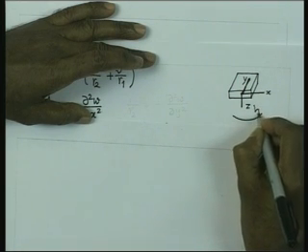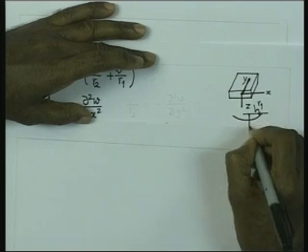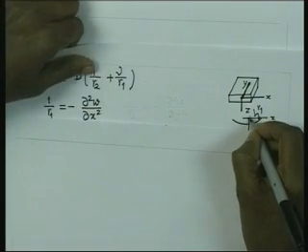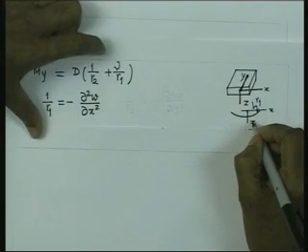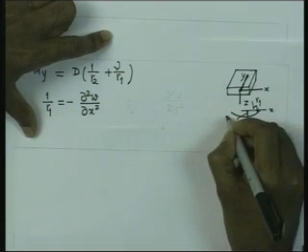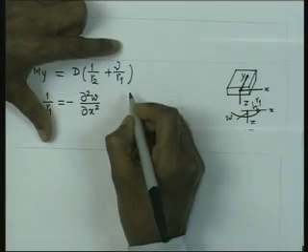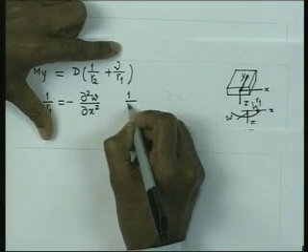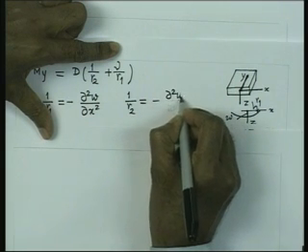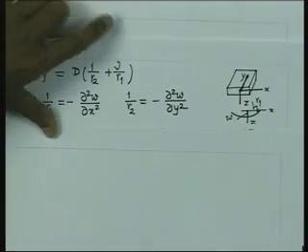So, this is what R1 is, and since the deflection is here in this direction and this is x, you get the double derivative of this deflection W with respect to x, that gives you 1 by R1. Similarly, 1 by R2 is equal to minus delta 2 W by delta y square.